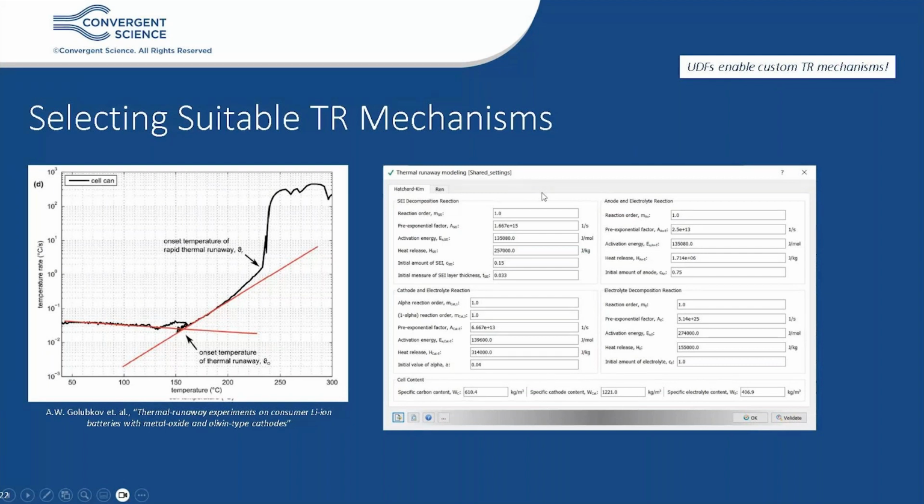Now, to note here, if you look at these thermal runaway reactions, you just have 4 to 6 or 8 reactions at best. The SAGE detailed chemistry solver has been used for more detailed reaction mechanisms, like thousands of reactions with thousands of species for fuel oxidation or fuel combustion problems. So it's very easy for SAGE to handle these reaction mechanisms, but at this point, they are not species-based.